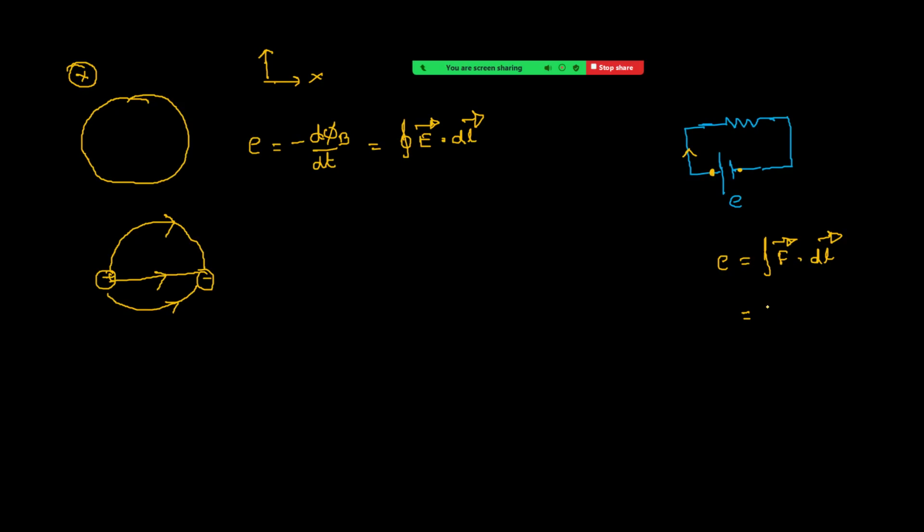That means in the place of F bar, it is now 1 into E bar. Electric force equals Q into E bar. Here we are taking, it is defined as the work done in moving a unit positive charge in one closed path in one round, right? That's why, taking the place of Q, it is a plus dot dl bar. This is what I have written here: closed integral E bar dot dl bar, right? Here E bar is now the induced electric field, which is non-conservative, right?